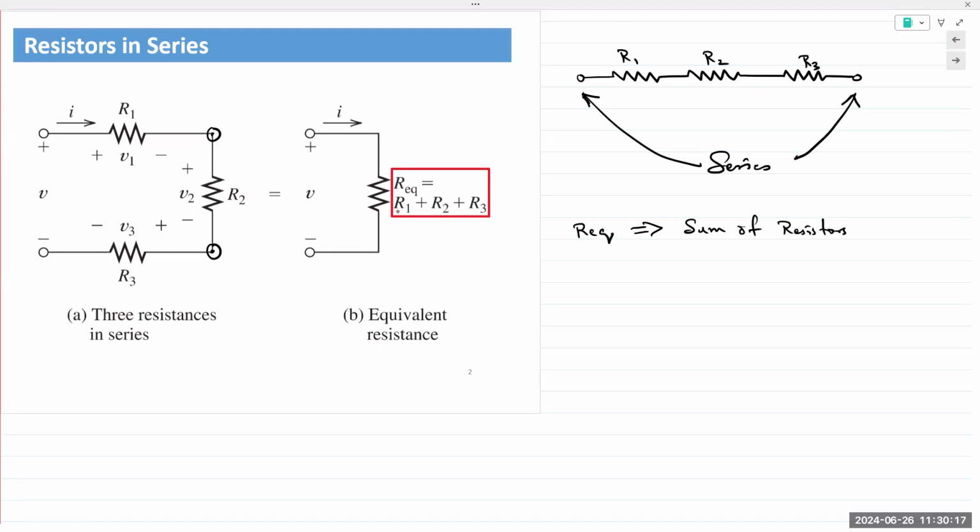When we say combine it together, this is just purely theoretical. But the physical basis in real life is that, let's say if you have three resistors, all 1 ohm each, 1 plus 1 plus 1, between the outer terminals, you can model it as an equivalent resistance or one single resistance of 3 ohms.